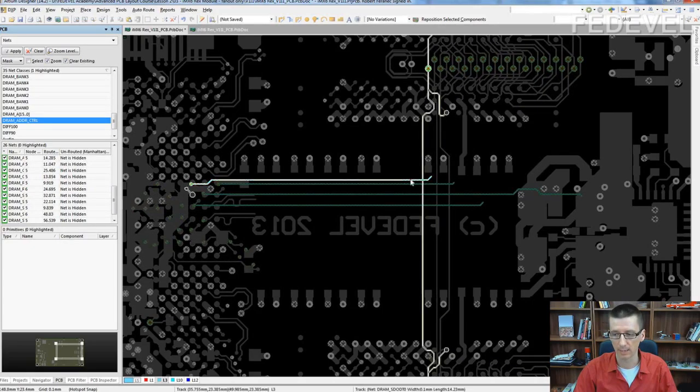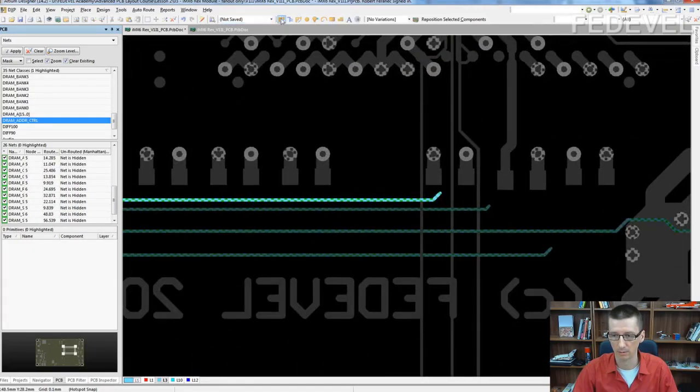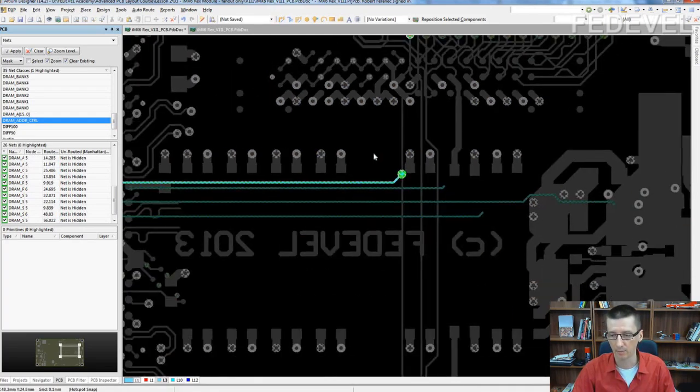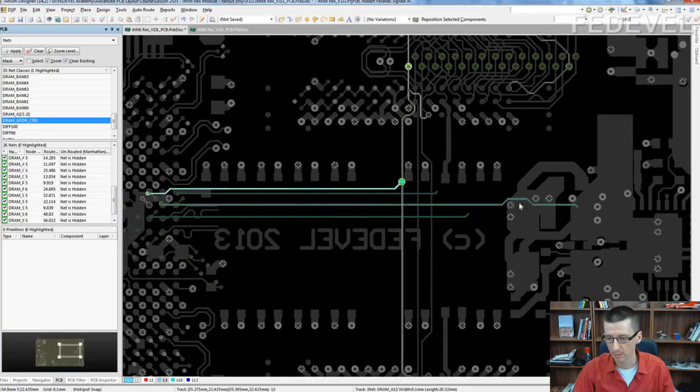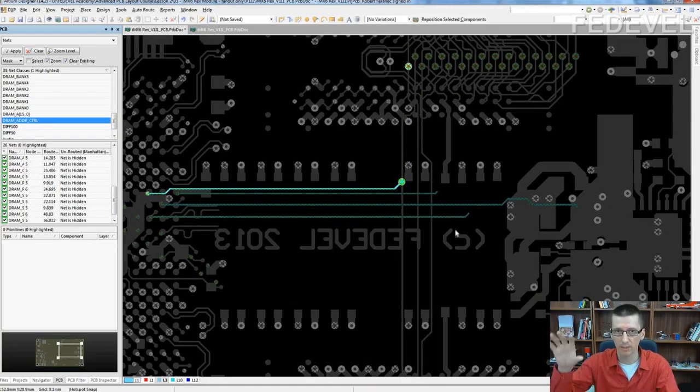These 2 tracks need to be crossed. So I just go here, yeah, and place the via here. It's much easier than if you have to move these connections later once you draw them and you need to fit some other tracks there. You need to keep moving the vias and tracks. Just draw them this way, and place the vias at the end.